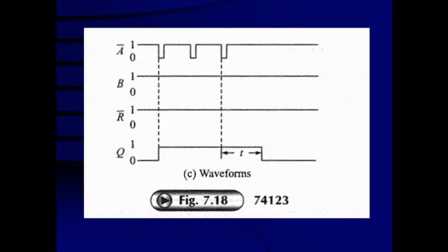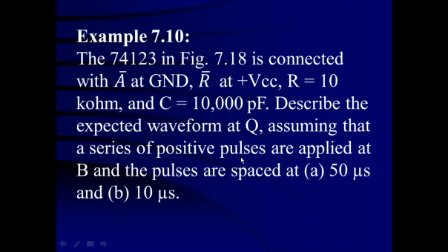So what happens is, already it is in the unstable state. At that time, a second trigger pulse is there. Again, it will be re-triggered. There is a third trigger pulse, again it is going to be re-triggered. But thereafter, there is no trigger pulse, so it remains high. So the timing begins from the last trigger. It will time out after this 0.33 RC time period, and it will come back to the stable state. So that way the clock period or pulse width can be changed using a retriggerable monostable multivibrator.